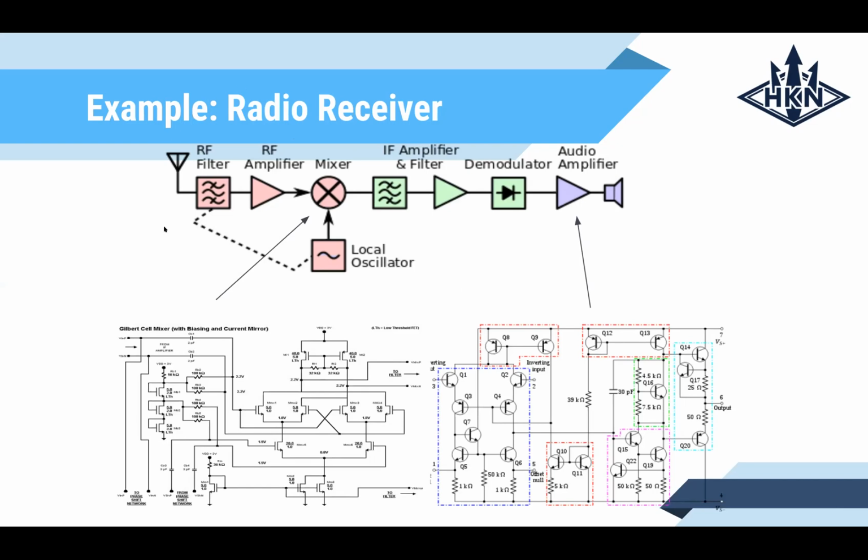So in your radio receiver, your radio frequency signal is input into the receiver and then processed through a filter. Then once it's filtered, we apply an amplifier. And so the thing that's very different about RF circuits versus what you may have learned from 35 up to 102 is that all your wires behave as transmission lines, and we can exploit that to achieve radical gains and make the signal much, much larger than we would normally be able to.